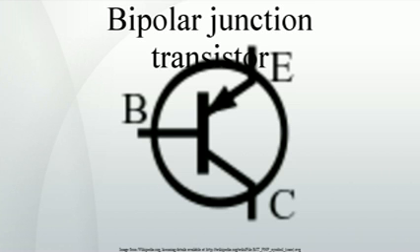This applied voltage causes the lower PN junction to turn on, allowing a flow of electrons from the emitter into the base. In active mode, the electric field existing between base and collector, caused by VCE, will cause the majority of these electrons to cross the upper PN junction into the collector to form the collector current IC. The remainder of the electrons recombine with holes, the majority carriers in the base, making a current through the base connection to form the base current, IB.